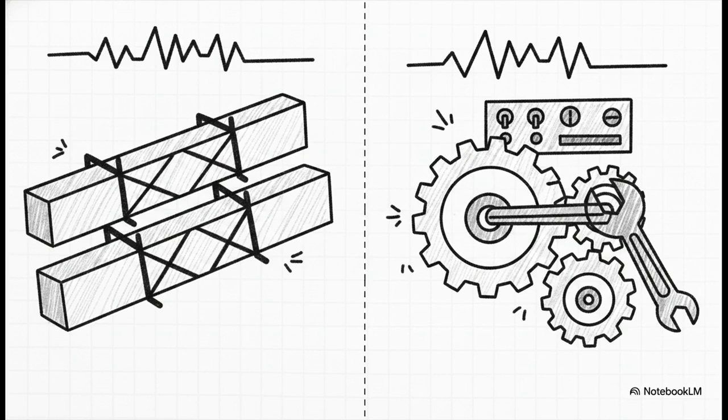Well, this is where brilliant engineers step in. During the design phase, long before the rocket ever makes it to the launch pad, they meticulously analyze all the natural frequencies of the spacecraft's parts. If they spot a potential match, they fix it right then and there. They might add stiffness to modify the structure's natural frequency, or they might program that reaction wheel to operate at a totally different speed so it never lingers at that dangerous 20 Hz. Basically, they intentionally detune the system, making absolutely sure those frequencies never coincide.